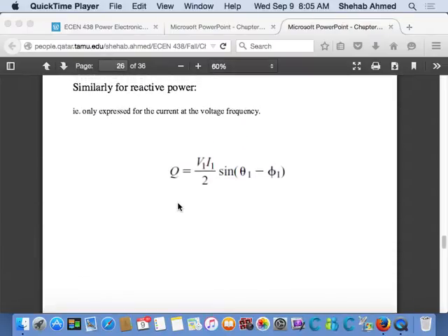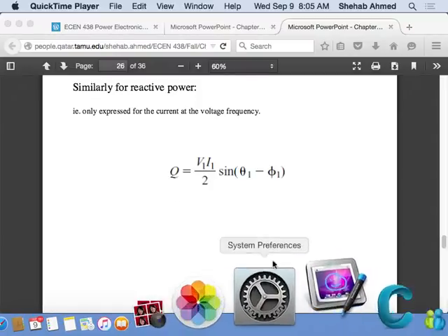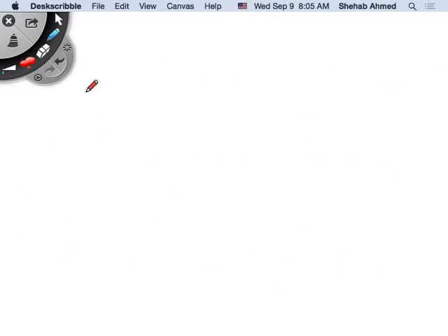Same thing. So if both are nonlinear, we have no common corresponding frequency? No, you can have. I mean, if both are nonlinear, it's fine. Your voltage source is providing the fundamental, third, fifth, seventh harmonic, applying that to a load that is responding also in a nonlinear fashion. What will it give? It will also give fundamental, second, third, fourth, fifth. Some of the components will correspond to some components in the voltage, and some components will not correspond.